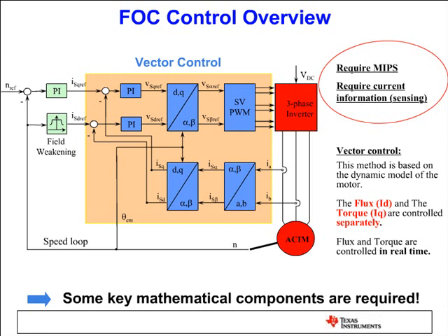Again, what we do, we sense the 3-phase current, convert it to 2-phase AC, and then convert it to 2-phase DC, which automatically decouples torque and flux components. Now, if you want to control the speed, of course, you need to close the speed loop as well, and then feed the error to the speed PID, and the speed PID will indirectly control the torque here. Because if you need to increase the speed, you need more torque. So the speed PID output becomes sort of a torque reference.